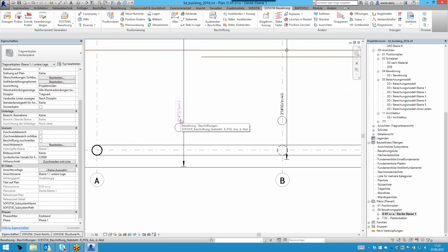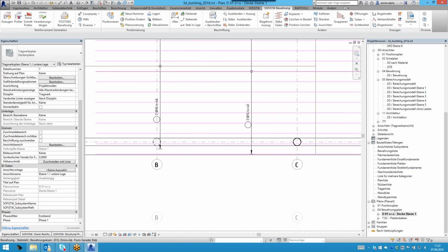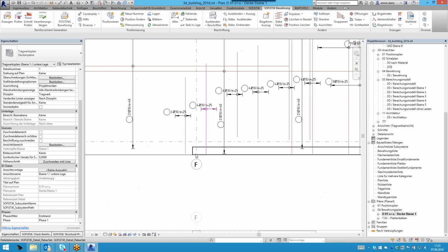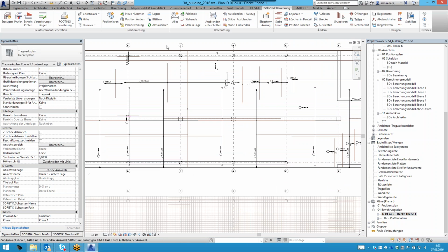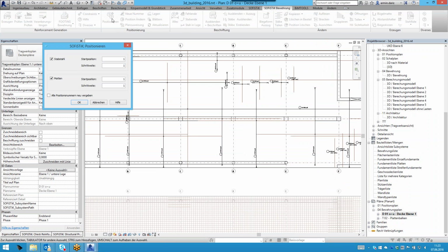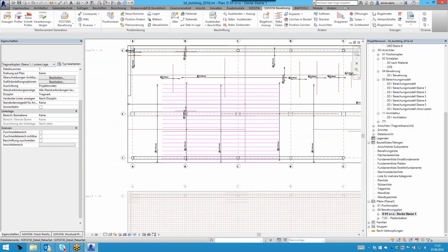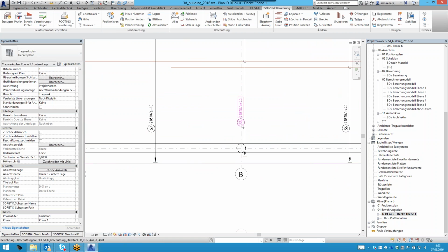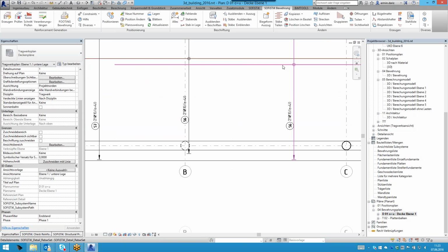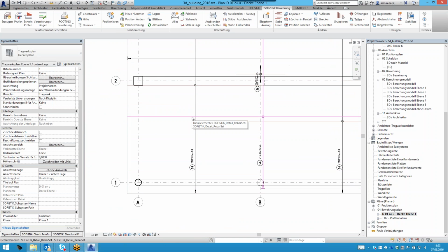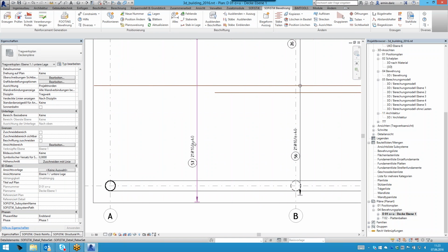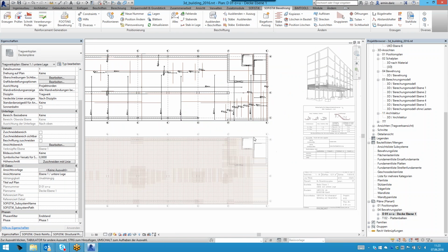You see here 21 pieces of diameter 10, each 40 centimeters and so on. You see also the additional bars appearing on the sheet. What we are missing again is the mark, so you can apply the marking as we have seen for the slab and the beam. You see that here also, same bars get the same number. So these are the 12-meter bars we have divided. We have at the start a 6-meter bar, so therefore this gets a different number, and so on.